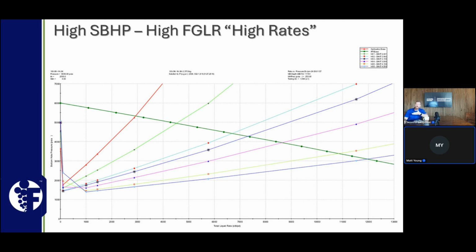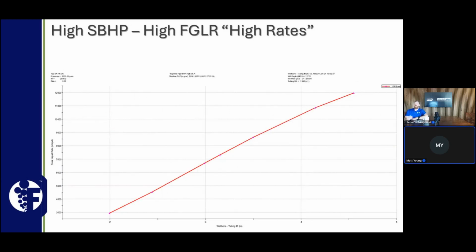this overall production. So what this tells me is that if my well's capable of producing these rates, a well like this is probably going to be a Delaware Basin well over in New Mexico, then maybe 7-inch casing, again depending on completion type, might be a good option, or possibly 5.5-inch casing with plans to casing flow the well initially and then tube it up with 2 3/8 tubing, or very small tubing, to help maximize that production.